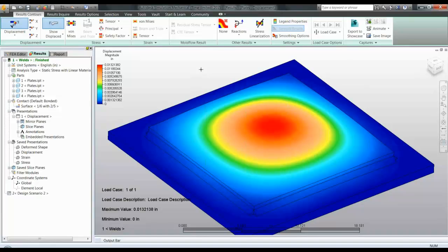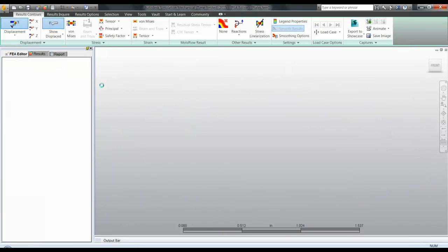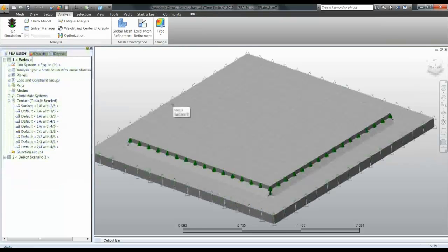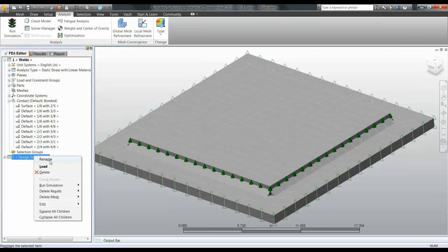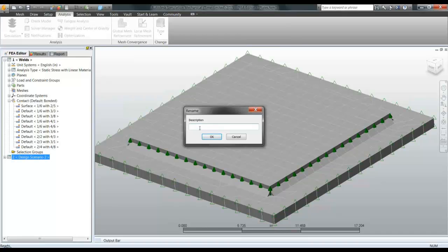So by using this welded contact, we're able to reduce our mesh requirements, especially as models get significantly larger, as fillets relatively become smaller and smaller compared to the global size. So being able to use this welded contact can help free up needed mesh density for more relevant areas. But the downside of it, though, is it does not allow you to directly view the stress in the welds. You'll have to do a little bit of hand calculations on the side to find out what reaction forces you have going through there and permissible stresses for your welds.